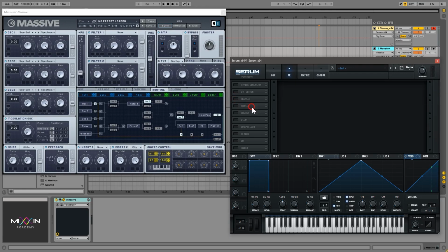Next effect we can go through is actually chorus. And I want to do that because a chorus is really similar to a flanger. The difference between them is that chorus actually adds more latency to that copied version of the original signal that it's adding back. So in this one, specifically, we have two of those delayed signals that we can introduce different latencies for and get a different result. So this is what a chorus sounds like. So without and with.